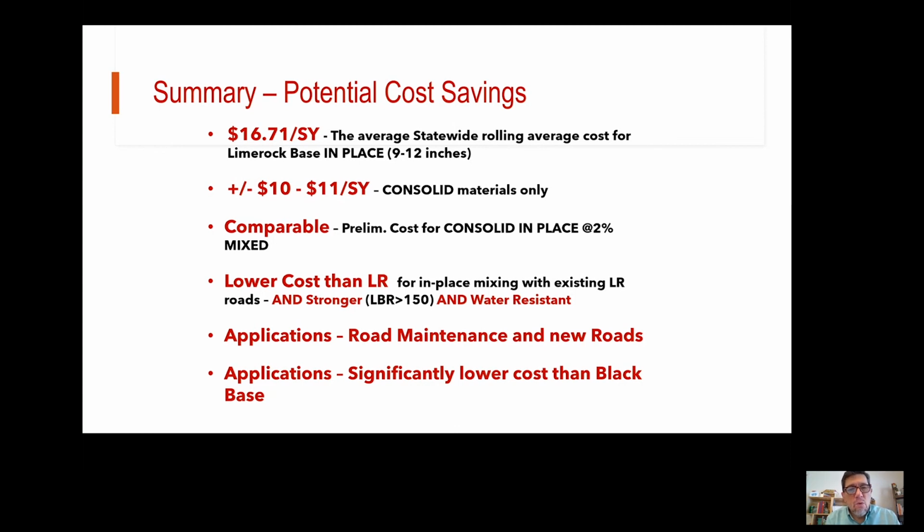Now, we believe that lower cost than lime rock is available if you're mixing in place and you're mixing with something that has existing lime rock in the road base. You only need 2 to 3 inches of that, but if you've got some lime rock, remember the strength test that we showed you earlier, you're going to get a strength that's greater than LBR 150, and it's going to be water resistant, which means it's going to last a lot longer.